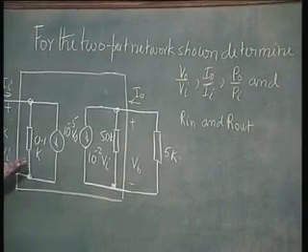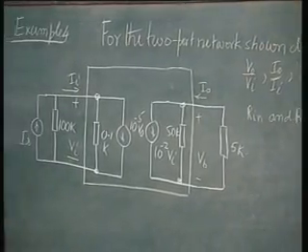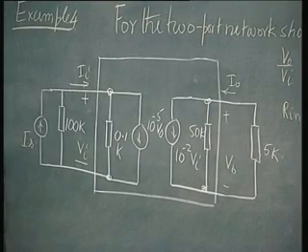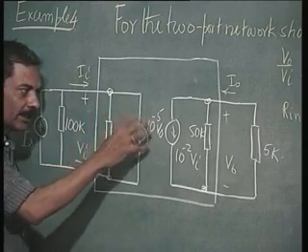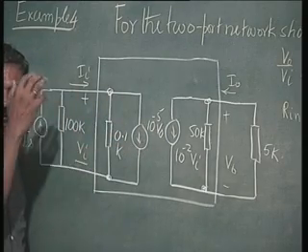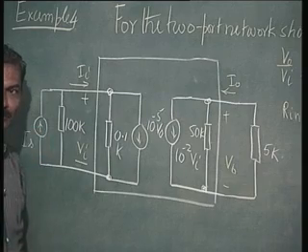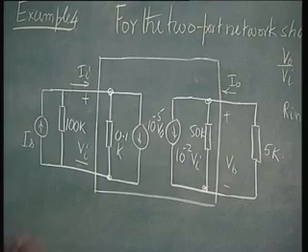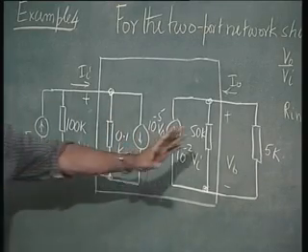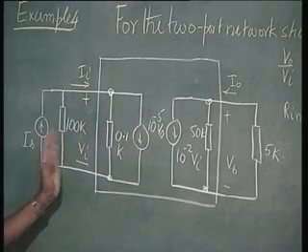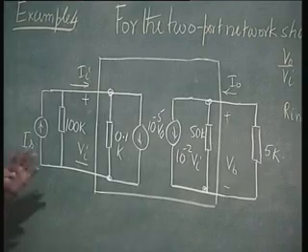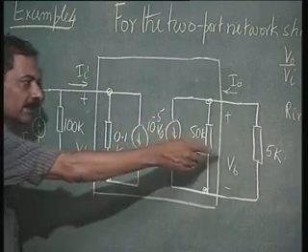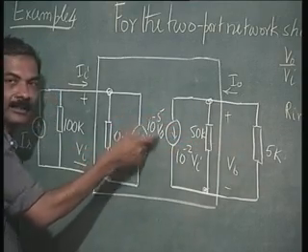Now the only difference between what we had earlier worked out in the amplifier case and this, the earlier amplifiers were all unilateral. What it meant was that YR or HR or ZR or GR was 0. So transmission was possible only in one direction, forward direction. Whatever was happening here was not getting reflected onto this side. Now we have put non-idealities everywhere. So here is the case where we have some reverse transmission. Whatever is happening here is felt here.